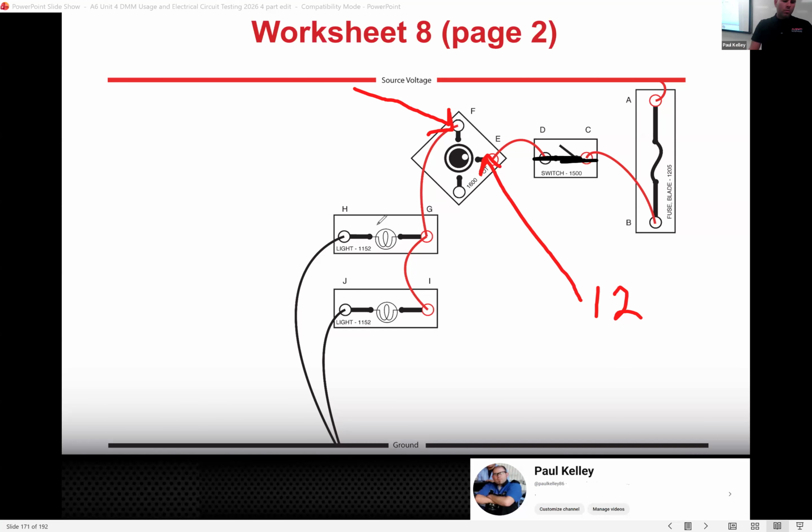Well, let's just say we did funny numbers, and let's just say the total resistance of these two was, let's make it 4 ohms. Not 4 and 4, but like if the total resistance, you remember how we did that long calculation of 1 over R plus 1 over R plus whatever. Let's just say that number came to 4. And let's just say this individual rheostat dimmer came to 4. The series part of the circuit is 4 ohms and the parallel part is 4 ohms. What should we have at point F?